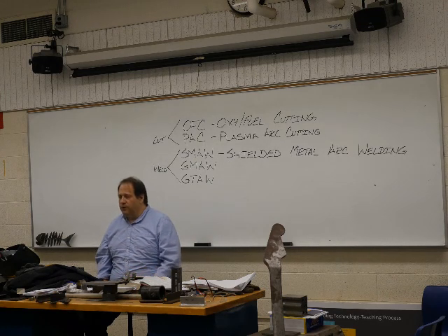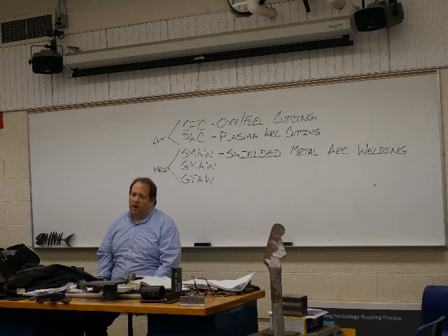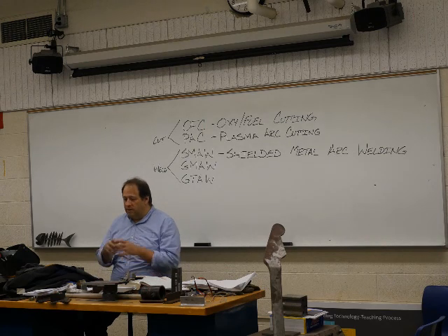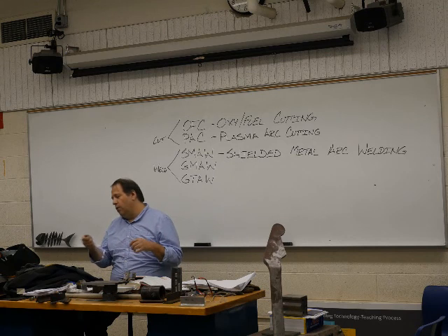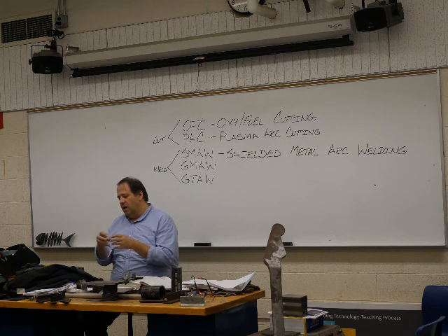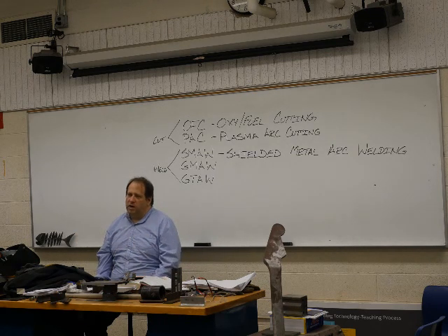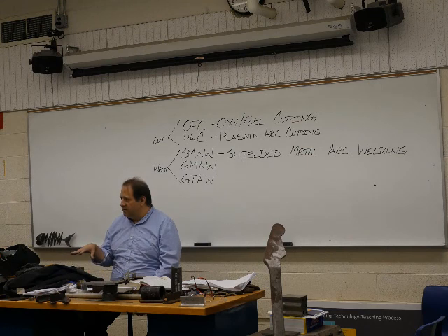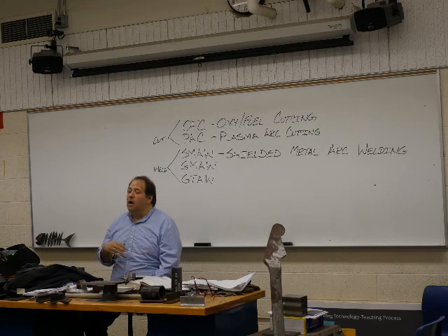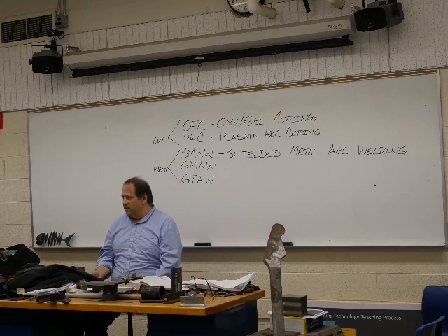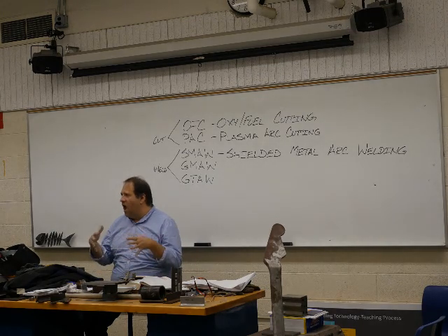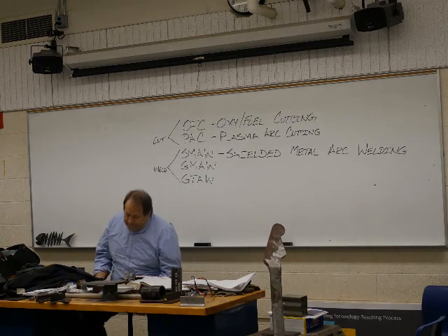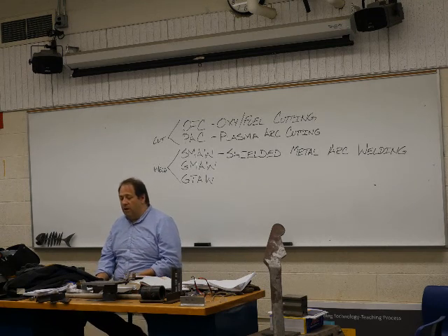It also will produce a slag. Slag is made there for a couple of reasons. One is to kind of protect it. As we move away, that gas follows us. It's a protective coating to keep the atmosphere out until it's solid. It also helps hold the heat in, actually, so it slows the cooling process down a little bit. By doing that, you're going to maximize the ductility of the weld so it doesn't crack. So that's where the shielded metal comes from.